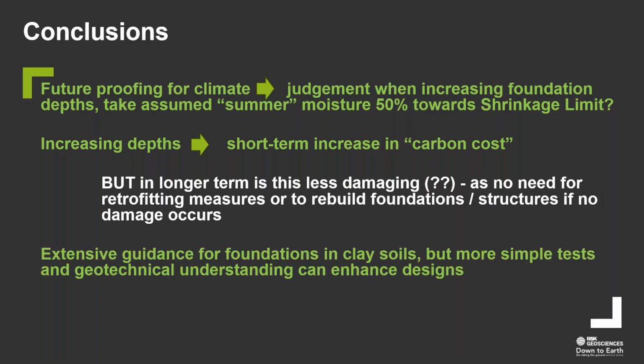An extensive guidance does already exist, and my advocate would be to carry out moisture content tests more, simple tests, closer to trees, further away from trees, at different depths. So more testing of the soil, but simple tests. It doesn't have to be complicated, and that will actually help no end.